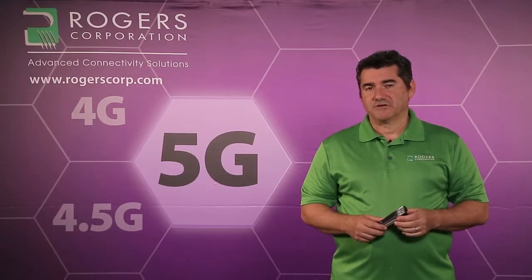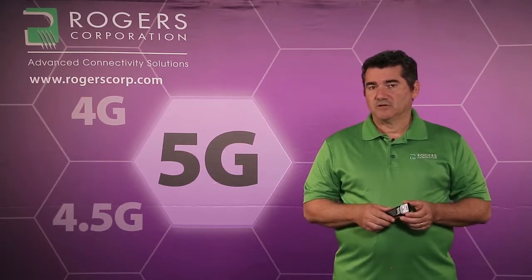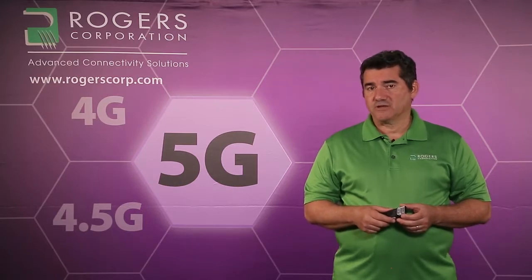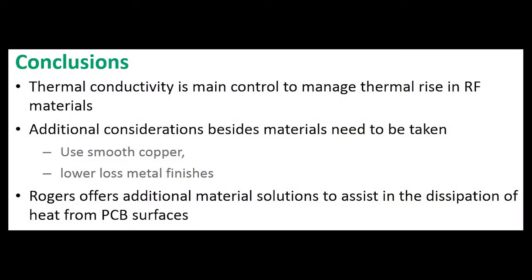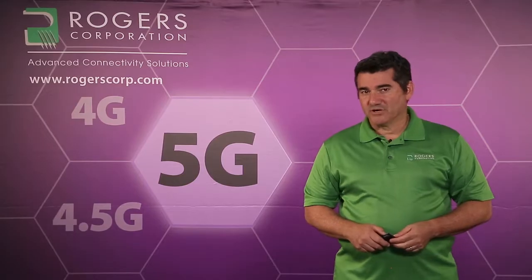As we covered in this series, electrical engineers tend to want to solve things electrically, with loss tangent and dielectric constant. We showed you some data that shows how thermal conductivity is very important, as well as other parameters like conductor roughness. So thermal conductivity is the main control to manage temperature rise in RF materials. Additional considerations besides materials need to be taken, like the use of smooth copper or lower loss metal finishes, which were not covered in this video. Rogers offers additional material solutions to assist in the dissipation of heat from PCB surfaces, like the product CoolSpan. This concludes this segment of the Road to 5G. Thank you for watching.